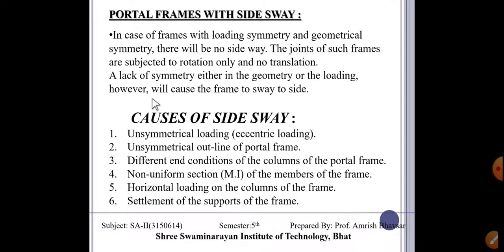Now here we are talking about the portal frame, right? Portal frame with side sway, or without sway. We have to consider which kind of frame is given here. If it is a sway frame, then the analysis is different, and if it is non-sway, then we can simply calculate it as a beam.